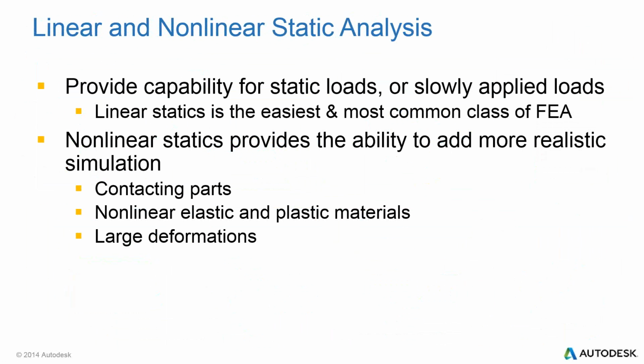So let's get into the analysis types that I want to discuss today. The most common one I think most people might use would be a linear or a nonlinear static analysis. We can do the linear static in Inventor Pro, but if you get into advanced contact types, or if you get into large deformations, a linear analysis just isn't going to be effective. It's not going to give you appropriate information.